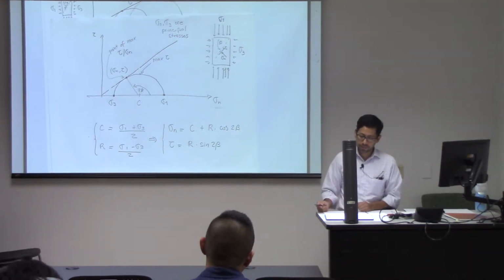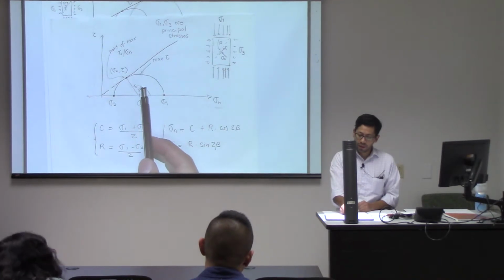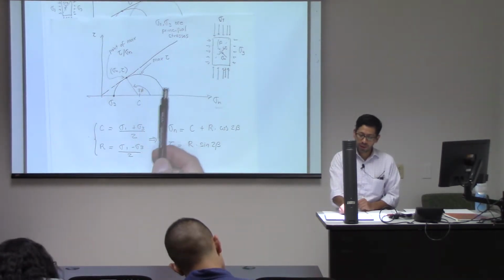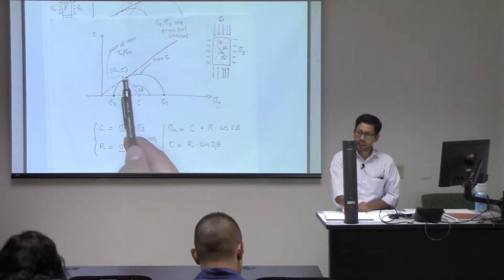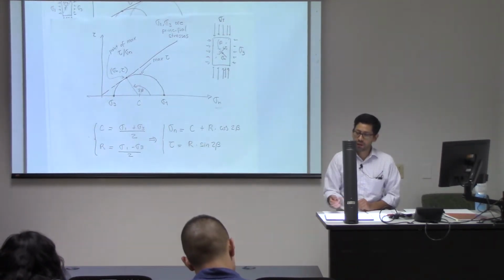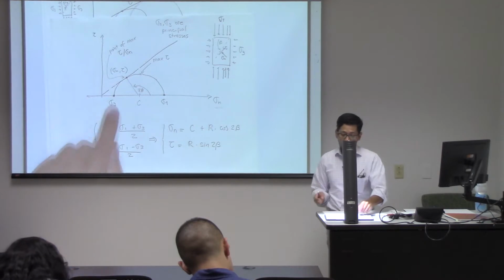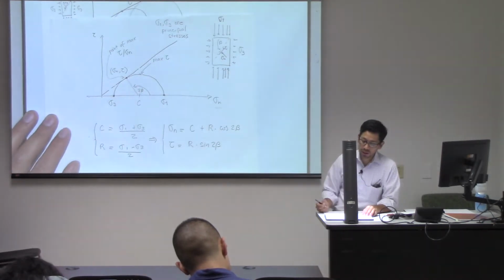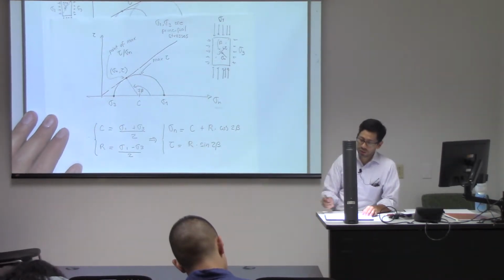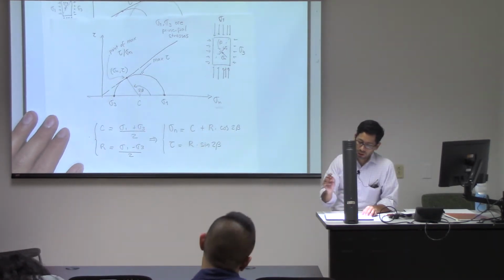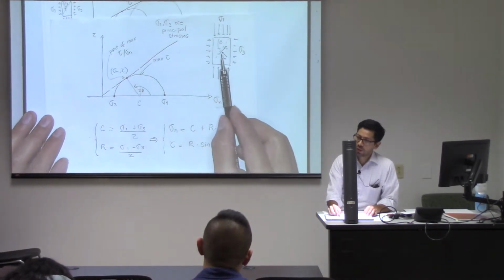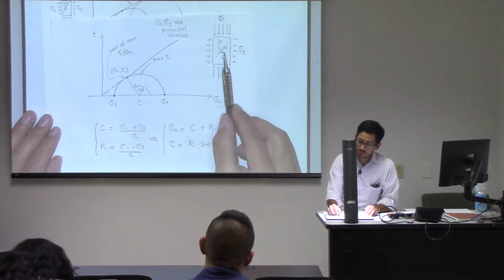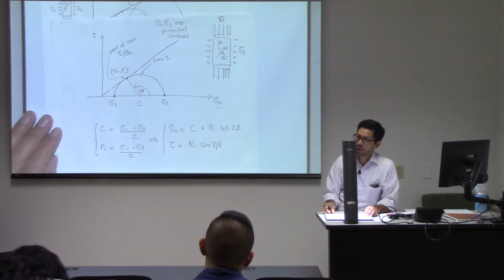And because of that, the size of the Mohr circle is going to tell us when we get closer to shear failure. And very important too, this point over here is also telling us the point in which there is a maximum ratio of shear stress to normal stress, and therefore tells us too what is the failure angle.